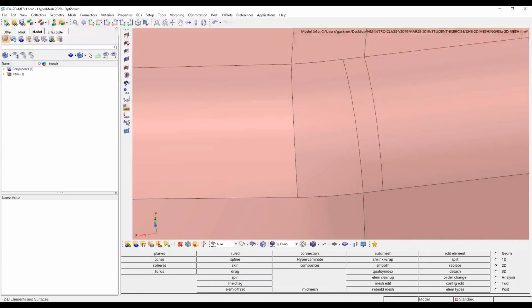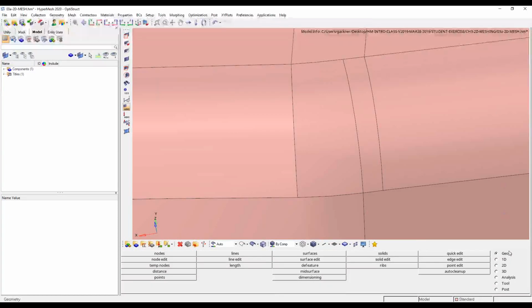And what I want us to start thinking about while we're going through this here is this idea that meshing is actually the easiest part. Clicking a surface, dropping elements on it, that is probably the easiest part to do. And it's kind of funky. I think yesterday, I'm sure I said it, and I'm sure you've heard it from other engineers in the past, that meshing is a skill. It requires a lot of expertise, but once you know what you're doing, that's the easiest part. What really is going to be maybe the trickier part or be a little bit more involved is the preparation leading up to your mesh with your surfaces and your geometry.